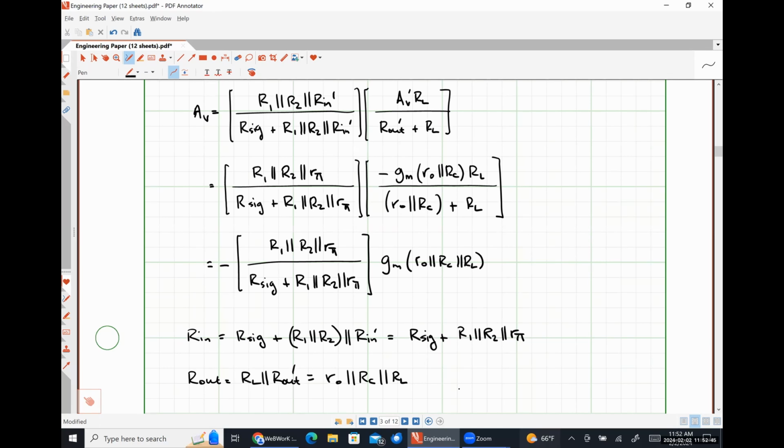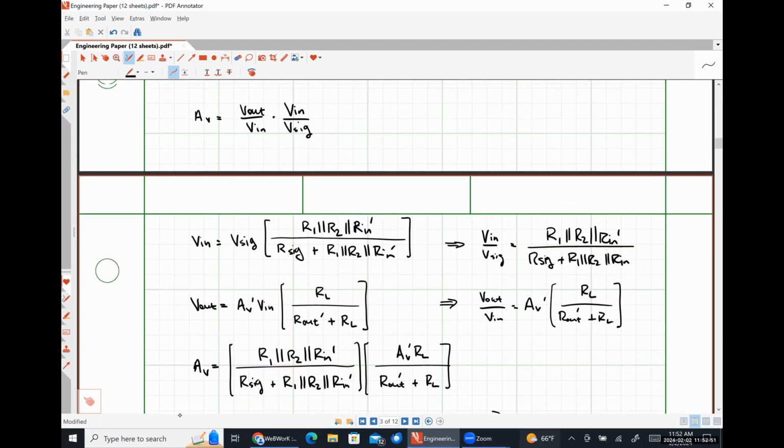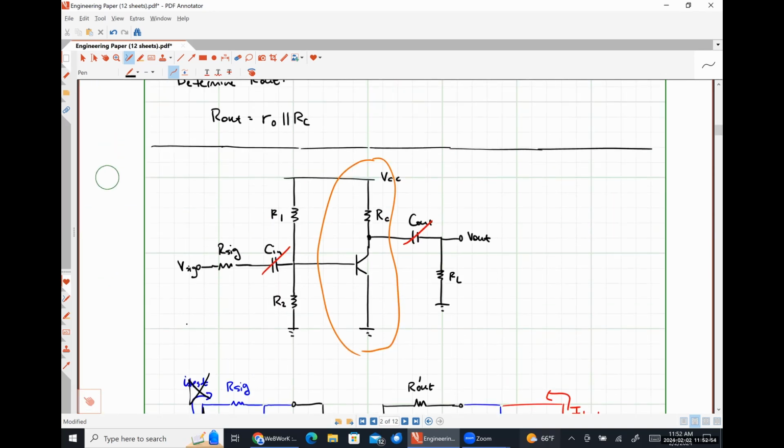Purely dependent on the value of the resistors that we use to bias everything. Because if we look at this original circuit here, we've taken into account the resistance of our source, the resistance of the voltage divider leg of our resistor divider network. We've taken into account the collector resistor. For this particular one, my emitter resistor is 0 because degenerating the emitter is going to add a bit of complexity on figuring out how the transistor part works, which is what we're going to talk about next. We've got our load resistor included, all of that kind of stuff. So we know what our voltage gain is with literally everything connected to the circuit in place, okay?